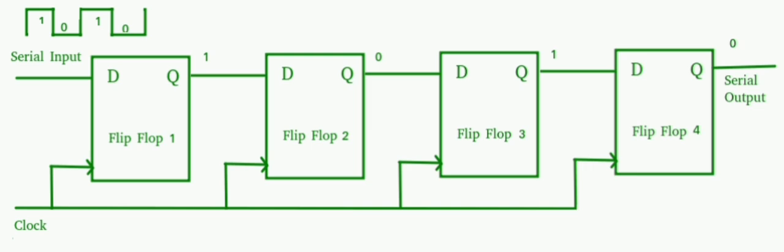Full scale output voltage VFS is the maximum output of the DAC: VFS = resolution × maximum decimal value = (VR / (2^n − 1)) × (2^n − 1) = VR. Percentage resolution = resolution / VFS × 100 = 1 / (2^n − 1) × 100. Error or accuracy: the maximum error acceptable in an ADC or DAC is 1 LSB, which is equal to the resolution.